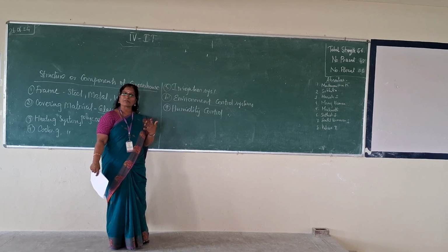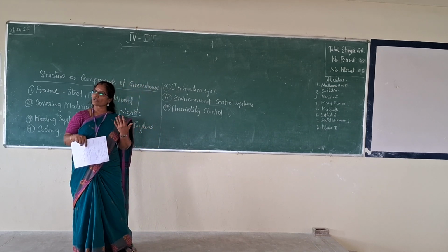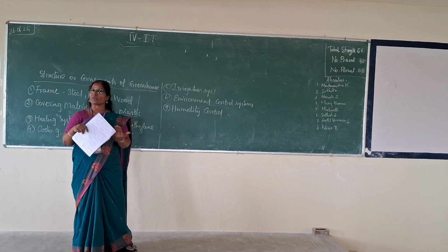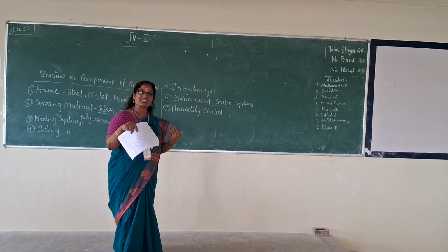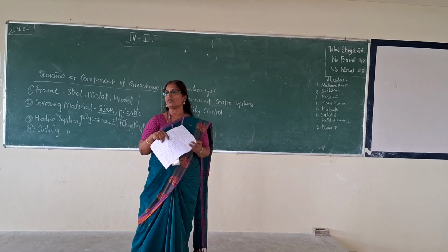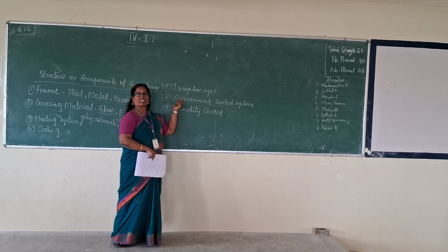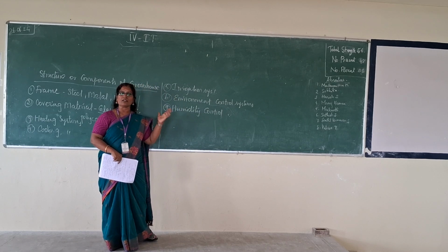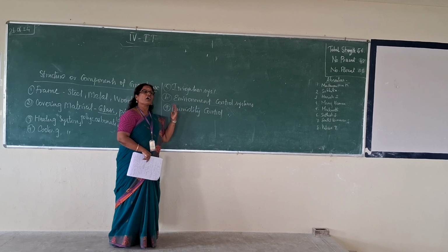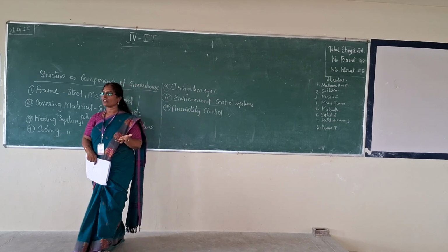If not, sometimes some crops will die, and we will not be able to analyze why the yield is not so good. Since we are exclusively establishing a greenhouse for plant growth, we even have to consider the amount of CO2 required by the crops and the amount of CO2 available in nature. Accordingly, we need to produce additional CO2 and provide it to the crops.